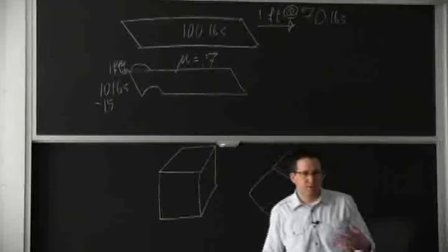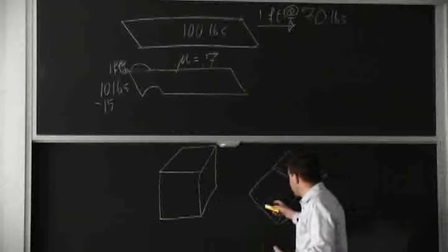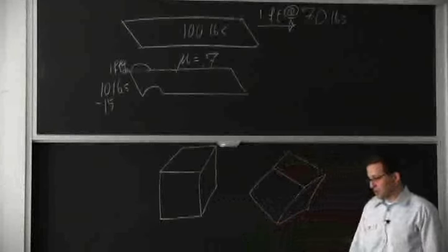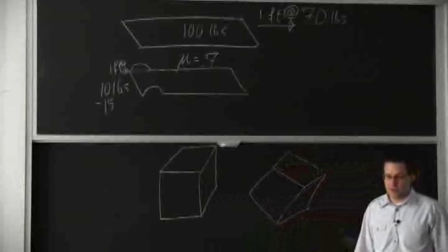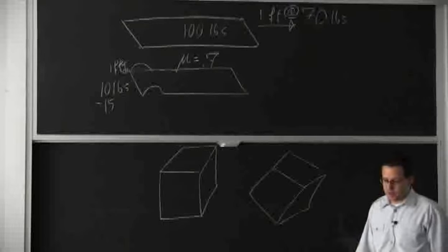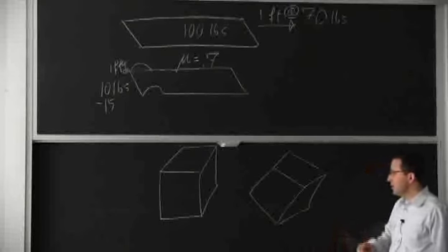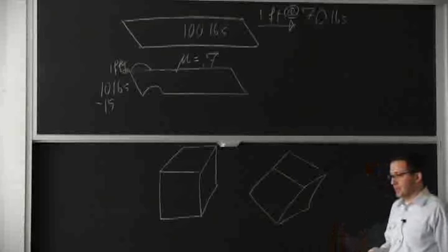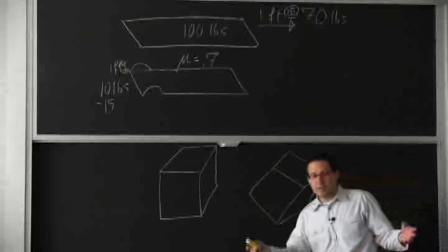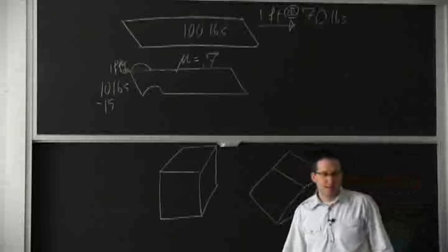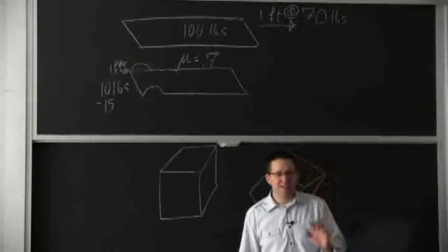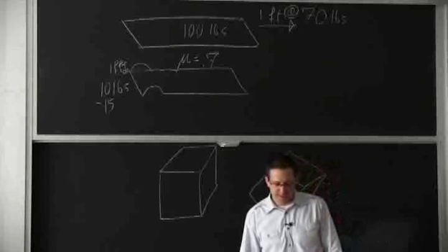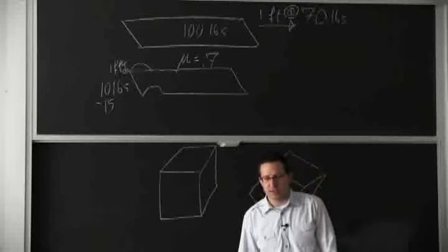It doesn't matter which way I draw it with respect to the material fracturing or the material hardening and all those phenomena, but for treatment, instead of having 9 components of stress, I only have 3. So it really simplifies the analysis, and that's the main reason we keep referring to principal stresses.